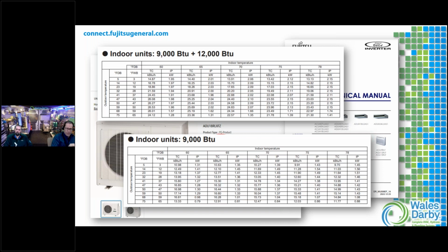There's another question that came in, John. Why or how does indoor temperature have a bearing on the BTU output? I assume they're really only based on outdoor temperature. In our inverter, the computer drives refrigerant cycles based off of loads. Load is outside, load is inside, and our set point, the comfort level of the occupant, off our remotes. All that is in the equation of how to run DC equipment. Using less energy is the goal, but providing that comfort.